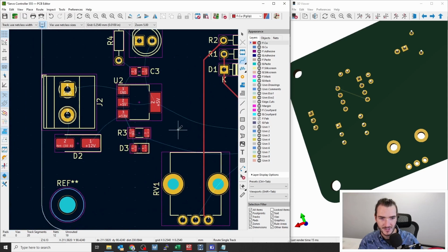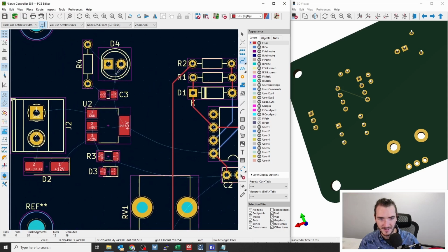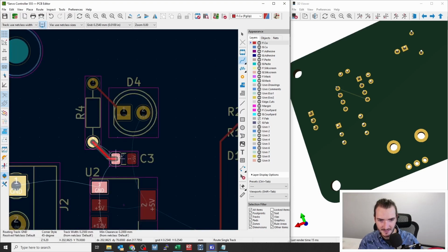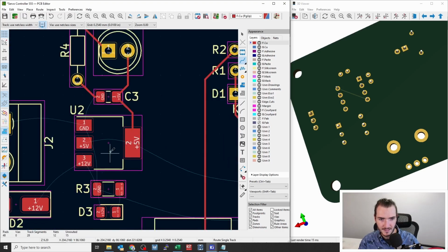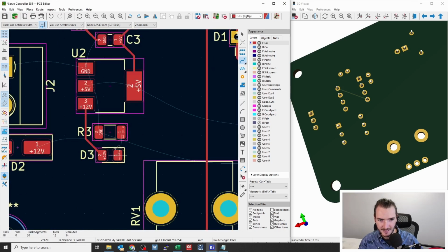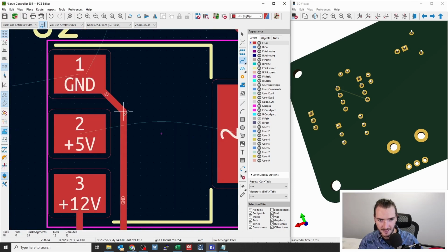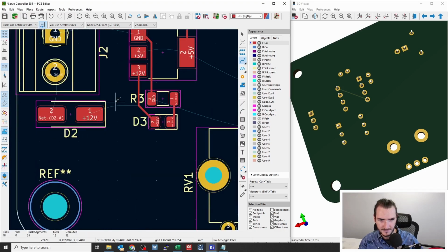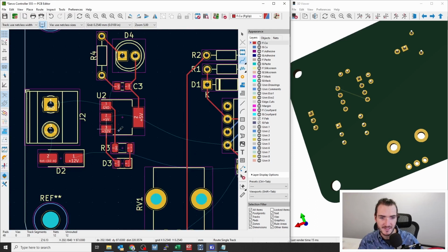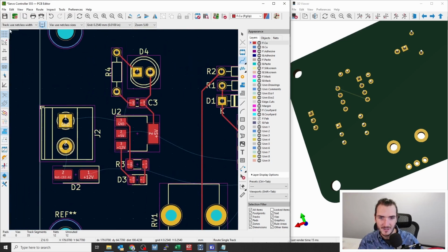All right, turning to our power supply side of things, I'll connect up this LED with its resistor, connect the power, 12-volt LED, connect that ground. And so this might be where we want to include some thicker traces, because now we're dealing with power. So I can go to track and edit the predefined sizes.